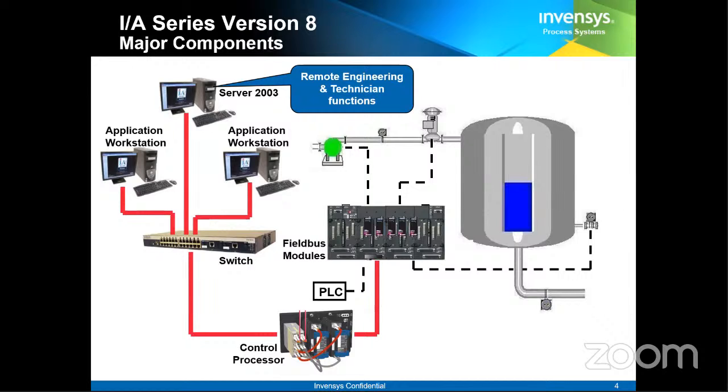So here, if the sensor fails, the sensor doesn't have the capacity to declare itself faulty. That is the basic behavior of a sensor. But smart transmitters are able to diagnose themselves easily. They can do their self-diagnosis. They can declare, yes, I am able to work or I am not able to work. That makes the life of engineers very easy. Let's say there are a lot of transmitters.